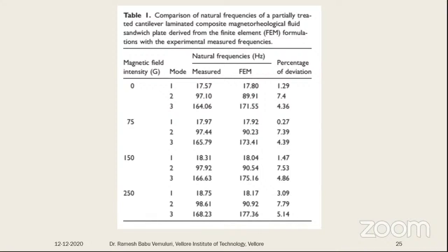For each element, the energy equations can be combined into a complete plate, beam, or shell, and for that we can find the stiffness and mass matrices, and using those we can find the natural frequencies. That's what I am simply telling. I will use MATLAB simulation for performing this finite element formulation of the analytical solution.